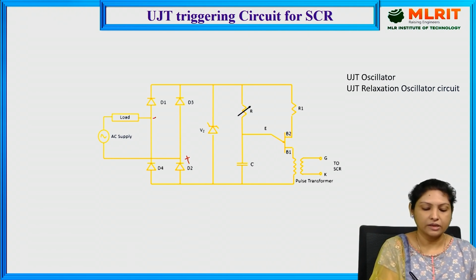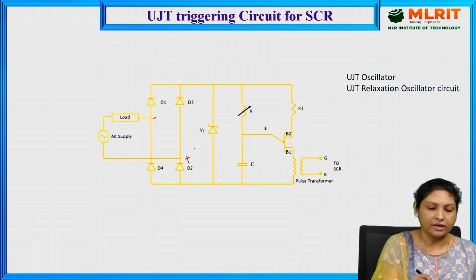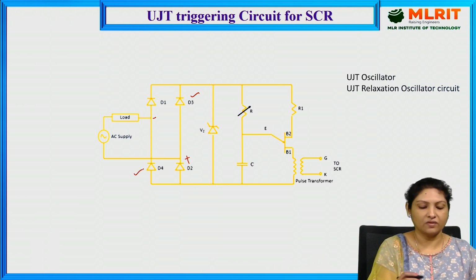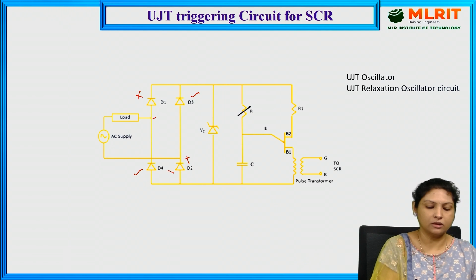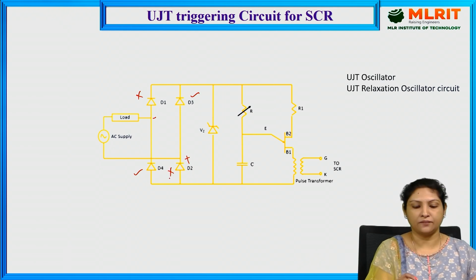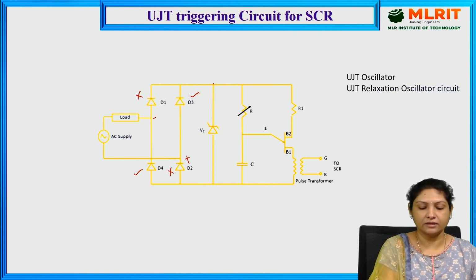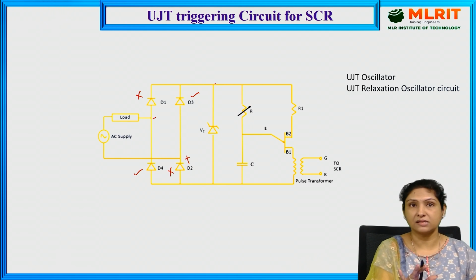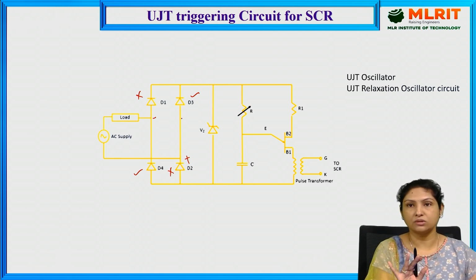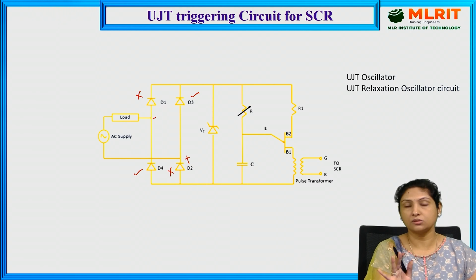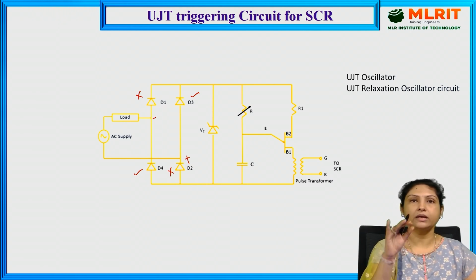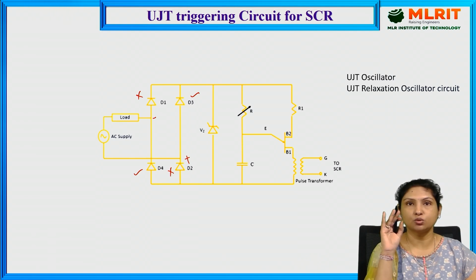That means, see here, diodes D3 as well as D4 will be forward biased, whereas D1 and D2 will be reverse biased. Now, D3 starts conducting current. As I already told you, if the rectifier is giving 5 volts and the requirement of the circuit is only 3 volts, in that case this Zener regulator clamps the voltage to the required voltage, so called 3 volts.